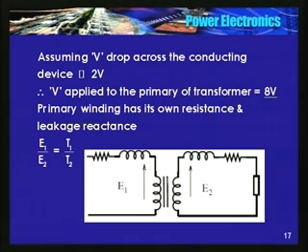Now since this is 8 volts and the current flowing is relatively high compared to the current flowing in this side, I'll assume that 1 volt is being dropped in this. Could be a conservative figure. So the voltage available at this point is 7 volts or so.